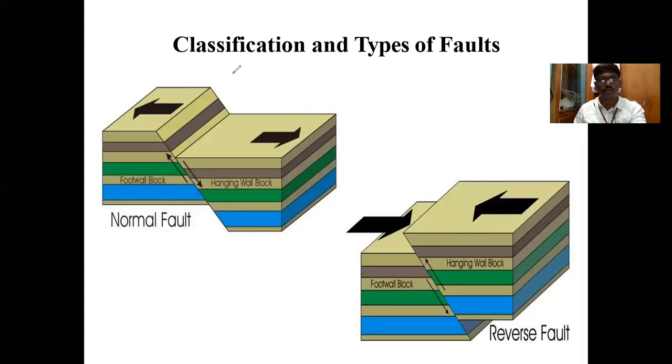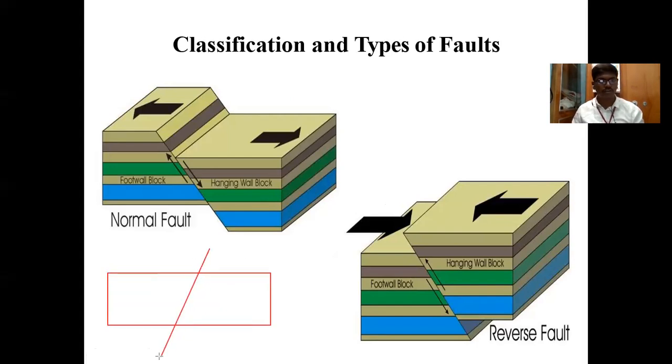Whenever I draw the figures, remember, I'm writing with respect to the parts of the fault which I explained. Like if I say here, this is the inclined fault, opposite to this I'm writing, so that you can understand the other fault plane. Whichever rests is the hanging wall, and whichever is below is the footwall. Since the hanging wall is resting above, if it is moving downwards and the footwall is moving upwards, then we say it is a normal fault, or what I said, a gravity fault. And the reverse of this, what happens? If I say the reverse of that, what will it be?